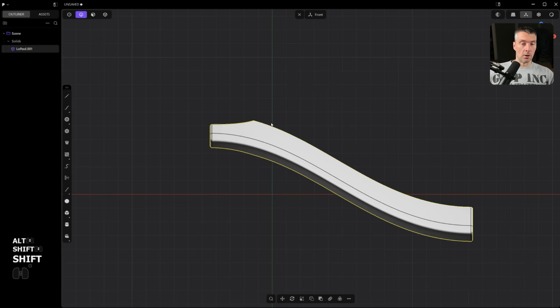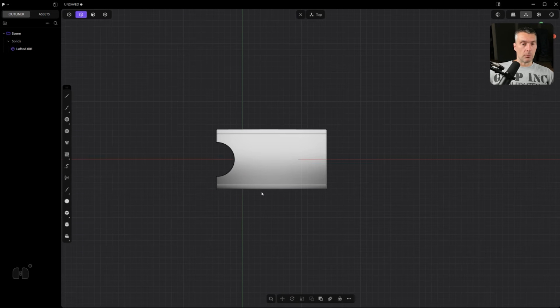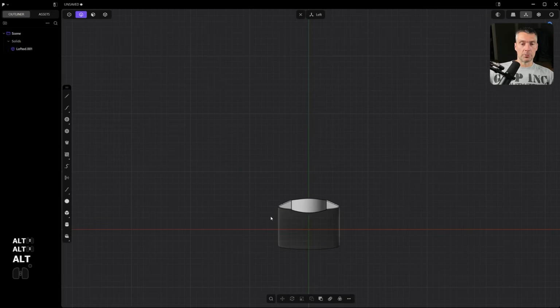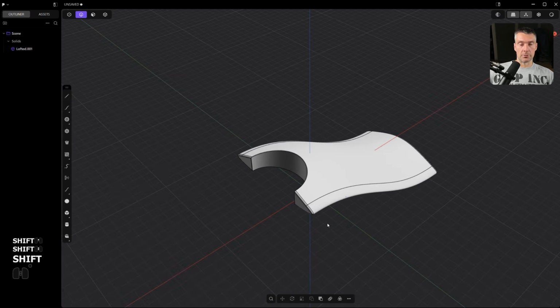Now, obviously, there's a lot more to it. So to sum it up, really easy. You've got curves, sheets, solids, and instances. You can use curves to create surfaces by lofting and patching or using X-nurbs. You can also create surfaces by booleaning, just like in Blender, using either solids, sheets, or curves, right? Like you've seen here, because you can use curves to cut stuff, right? And you can combine them all together to create stuff like this. For example, you can use a curve to create a shape, and then you can use booleans to drive cuts. And that's basically how you build stuff in Plasticity.